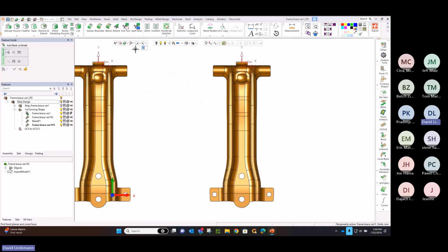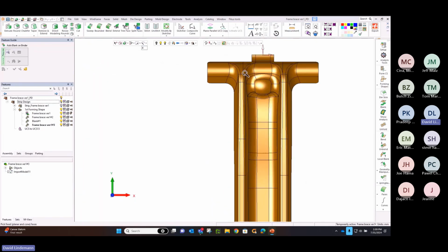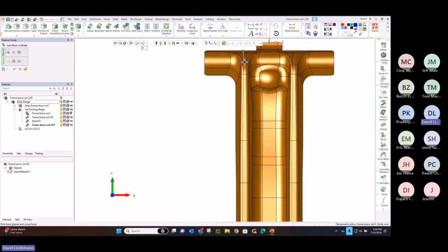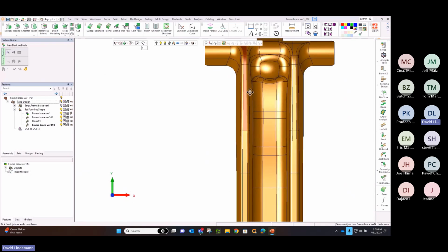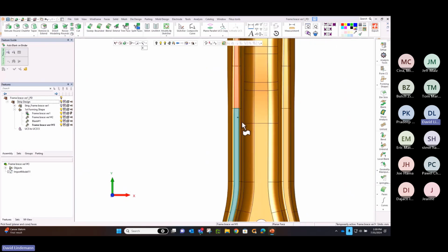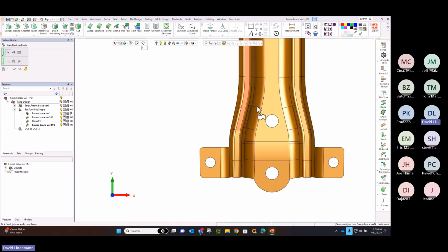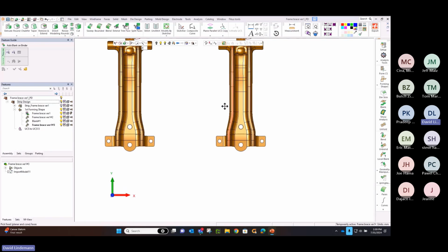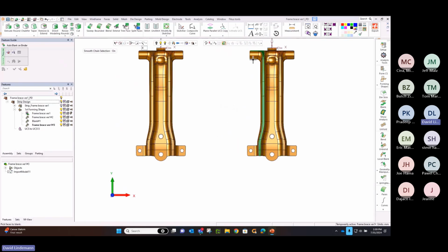I see the outer flanges. I need to bring those toward the blank. So I'm just going to pick these surfaces to unfold to. I'm using the little paintbrush tool just to swipe my way down through there instead of multi-picking all those different little faces. So that's what I'm going to develop out to. And then I pick the flange. It knows the material side. It knows the material. And I just say, go do it.